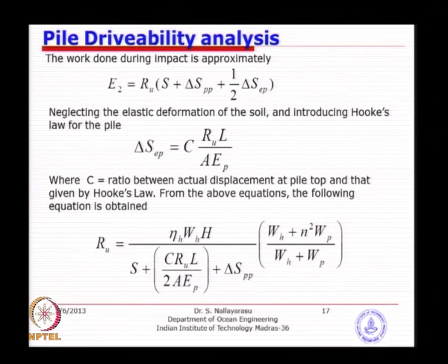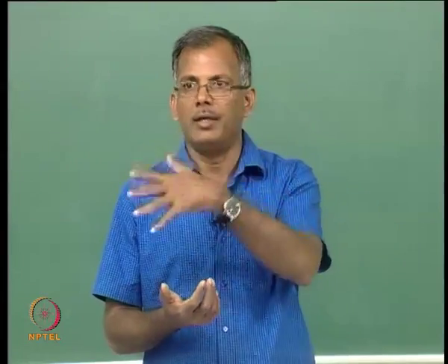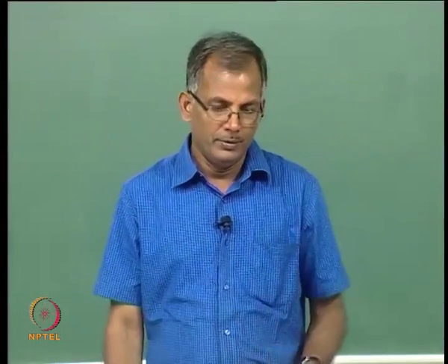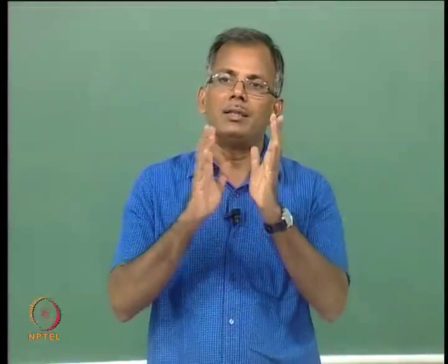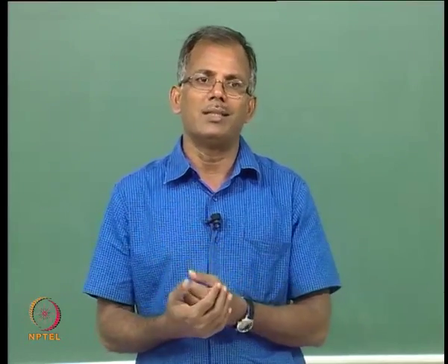So, that is exactly the idea of the dynamic pile driving formula, which is very simple. As long as you know the weight of the hammer and the fall height, which is the energy, and you have the resistance computed from your soil mechanics calculations, where pile diameter is given and soil layers are given. The only thing is you need to find out what the resistance could be at the time of driving, which I think we discussed in the last class.